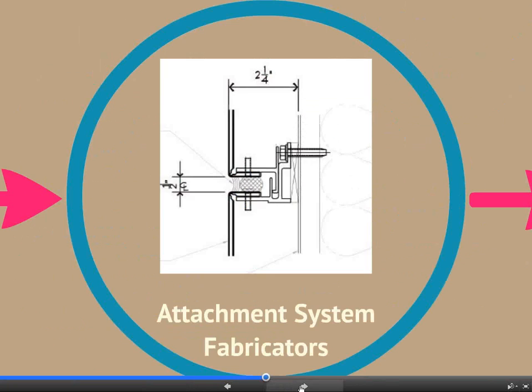Okay. So what is it that you wanted to talk to, going back to this detail again? Oh, well, just that this illustrates some things that you'd already talked about, the route and return, where they route out the backside of the panel to make it easy to bend, so you can get a real nice, sharp, clean bend. Chuck Coleman asked the question, could we not insulate the composite panel and have that serve as continuous insulation, like H.H. Robertson? And that's true.